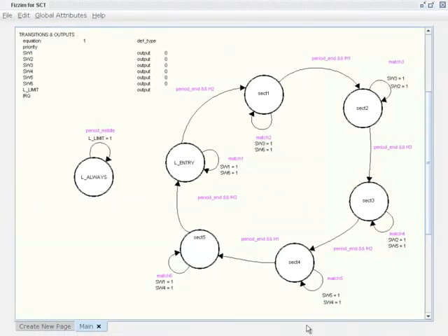As you can see, there are a total of 6 different states which are associated with each sector the motor will rotate into. The transition events between those states are defined to happen at the end of each PWM period, but will happen only when the Hall sensor feedback signal will have the appropriate level. For each of those states, the event named period middle will limit the timer. This event is associated with the middle of the PWM period.